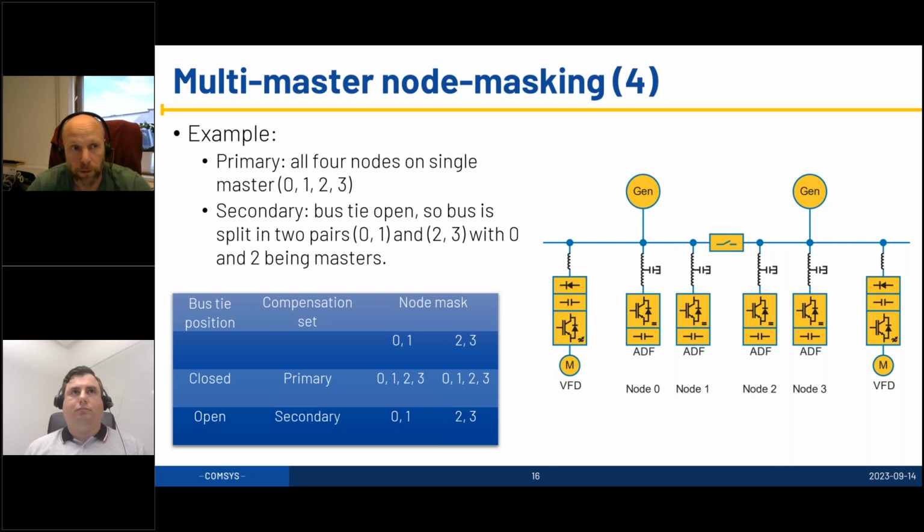The other reason is that the fault current is predominantly on the fundamental, and impedance control is a harmonic, meaning that yes, we are lowering the impedance on the harmonic. But consider, for example, if you have the 17th harmonic and you have a grid that is purely inductive, it means that on the 17th harmonic, the grid impedance is 17 times higher than on fundamental. But in this case, we do not have a resonance. So this is not really interesting for us.